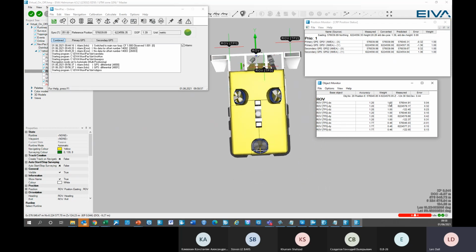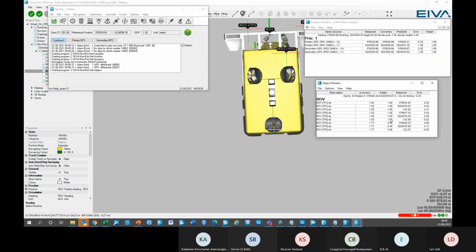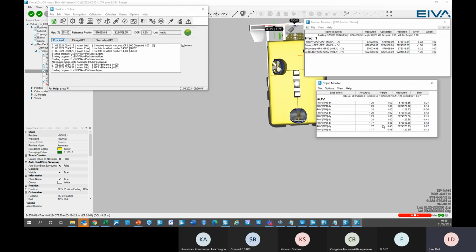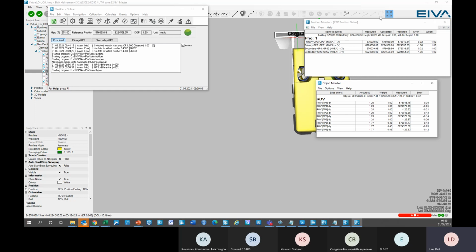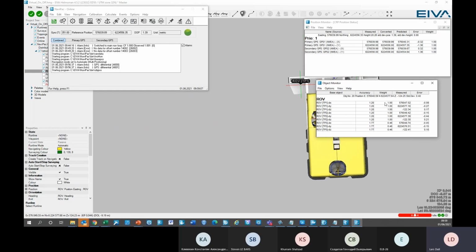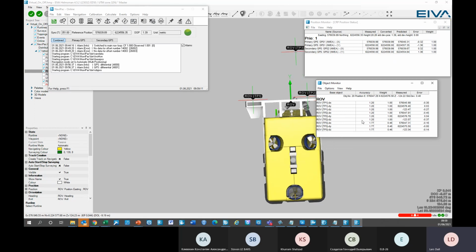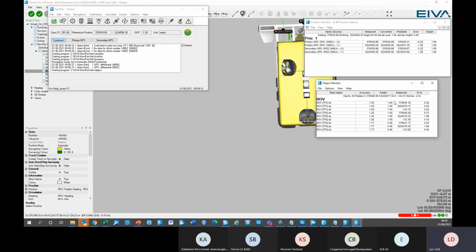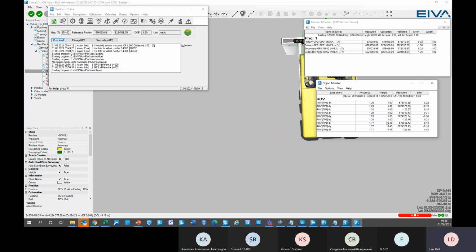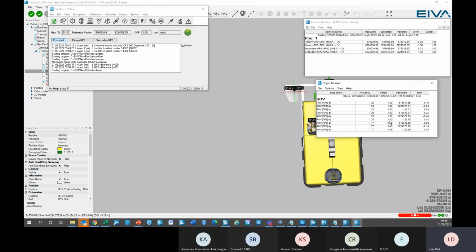Navipack will calculate the weight. Basically, the weight is calculated the same way we're doing it up here, relative to the inverse of the square of the standard deviation that we have here. So basically, it will take the lowest standard deviation and give it the weight 1.